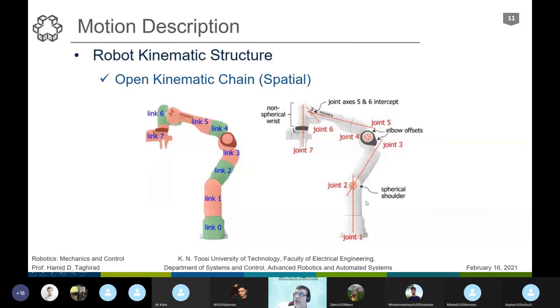And in many robotic designs, we have an RRR structure, but not an RRR in a plane, rather an RRR out of the plane, the spatial case. As you see again, for this motion, we move from outside the plane like this, and the other two joints provide us reaching to different points. So we can move the base, and then we can reach different points. These 3 degrees of freedom can provide us a reachable point x, y, z in the task space, as we call it.